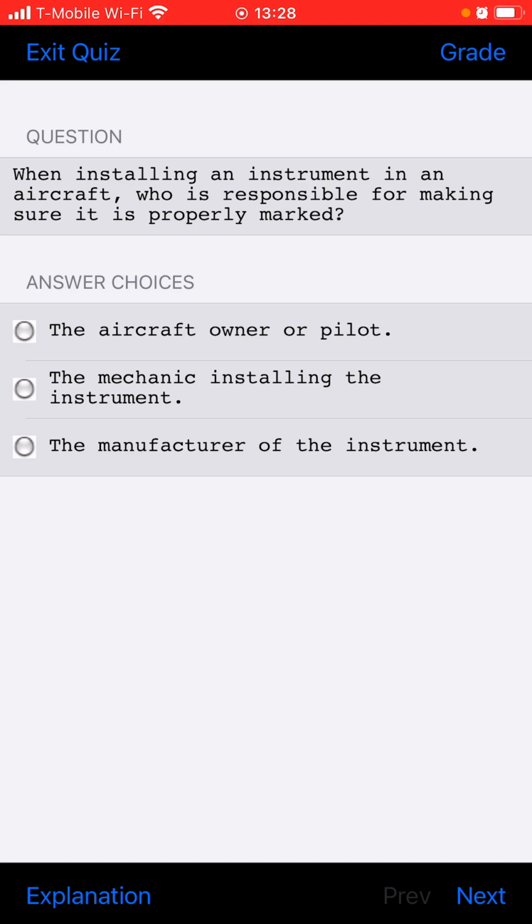Describe the operating principle of a continuous flow oxygen system. High pressure oxygen flows from the storage cylinder to the pressure regulator, where its pressure is reduced, and then to the mask outlet whenever the system is turned on.